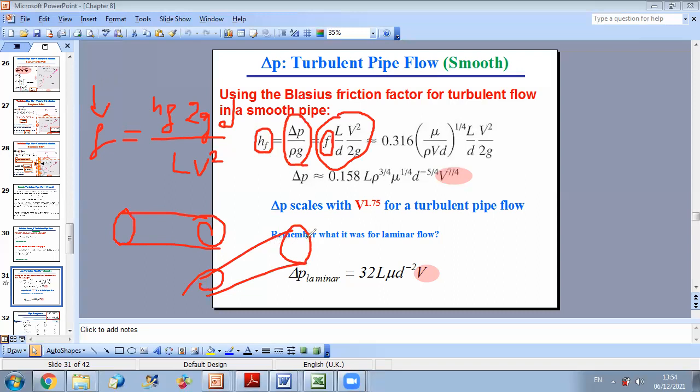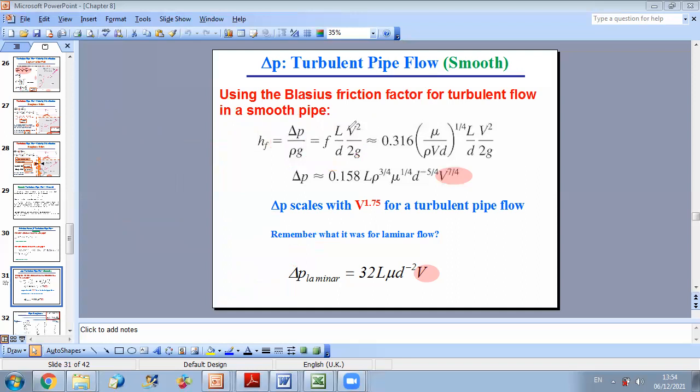If you have a flow moving down, the gravity will help you move your flow, while if you move up, in addition to friction, you should overcome gravity. This is why we defined last time a modified delta P accounting for gravity effects in case the pipe is inclined.